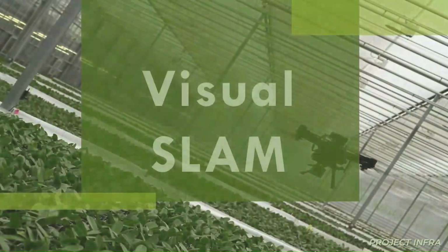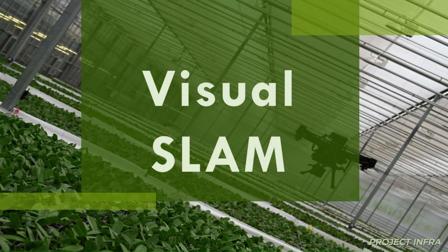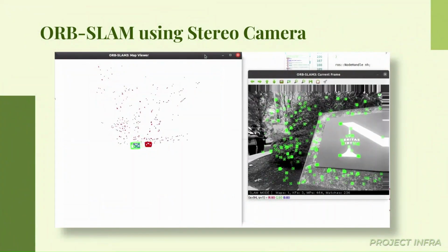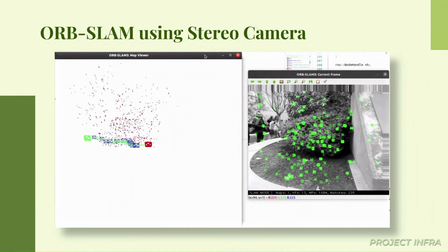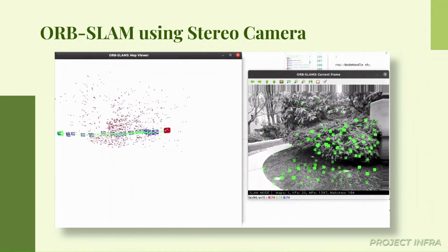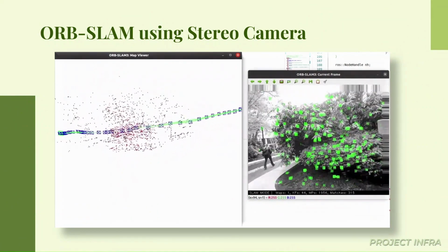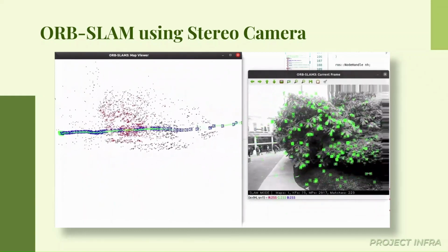As previously mentioned, our system also performs the vSLAM and we use the ORB-SLAM algorithm for it. This is where we mapped a small area outside the Snell library. We're performing vSLAM not just to help navigate the robot, but also provide a location of the images we captured using the NoIR camera.